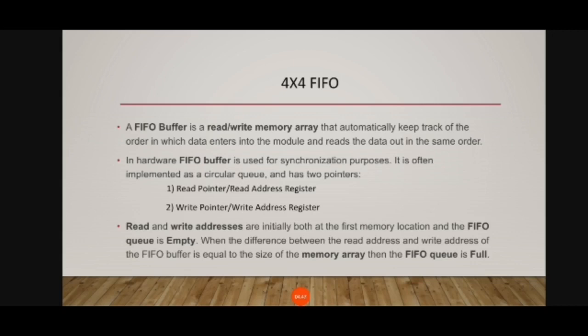Read and write address are initially both at the first memory location and the FIFO queue is empty. When the difference between the read address and write address of the FIFO buffer is equal to the size of the memory array, then the FIFO queue is full.